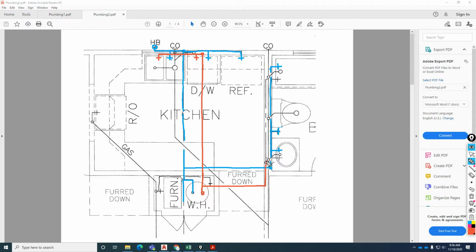Hot water continues from here, comes up out of the ground. And then here we go again with providing hot water for the sink. Do we need to provide hot water for the water closet? No. The water closet runs on cold water. Your posterior does not need a steam bath, so you do not need hot water for the water closet. That's a joke, but that is true. You don't need hot water for the water closet. And then the hot water for the tub. Okay. So that's really pretty much it for hot water and cold water.